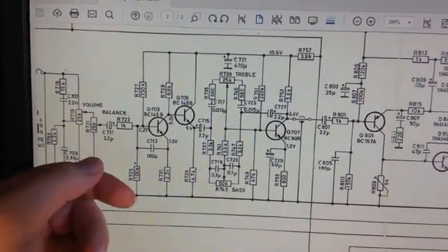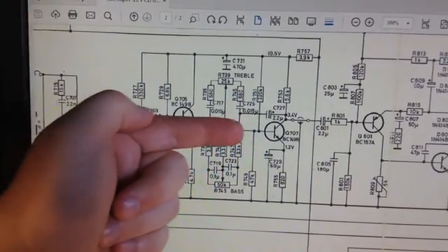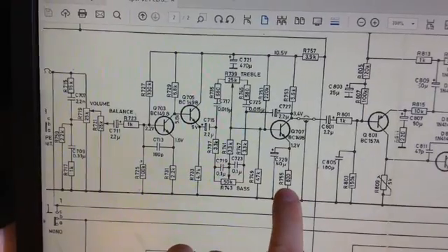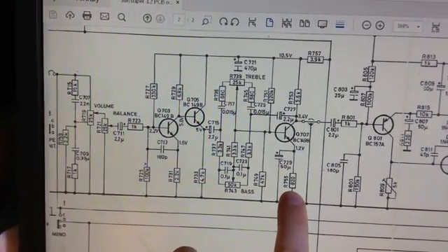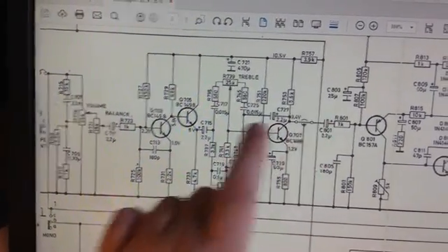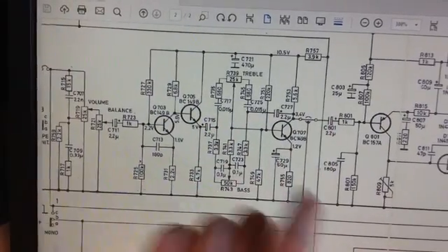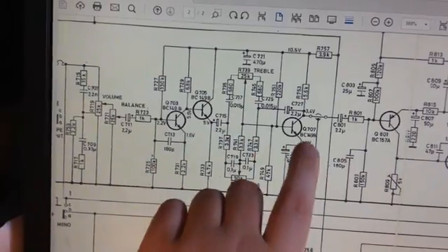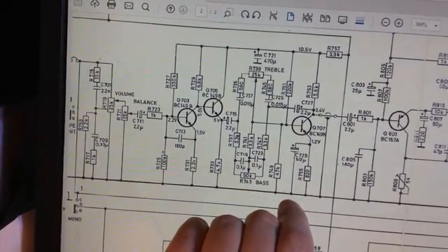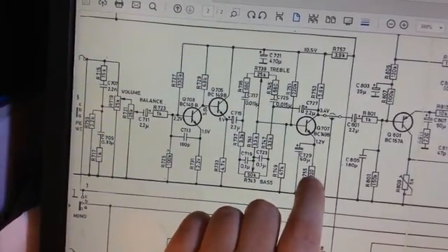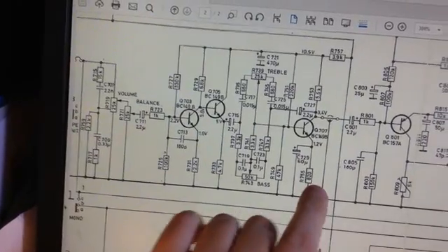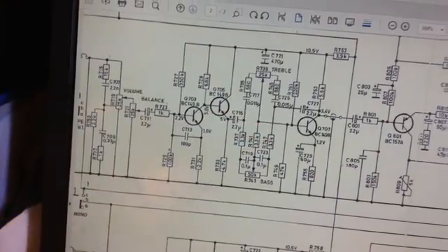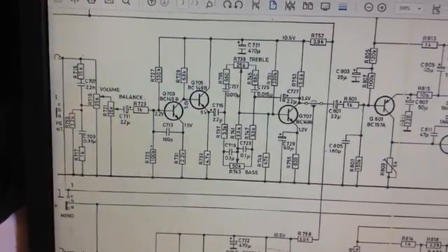But there's a problem though, because when you get a signal in which is AC, this resistor will provide a lot of attenuation, so the signal would not be amplified much. So what you do, you put a capacitor here such that the AC signal will have a path to ground. It basically bypasses this one, but for DC, this one will provide the stable voltages.